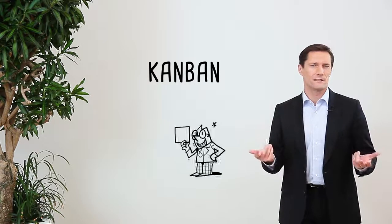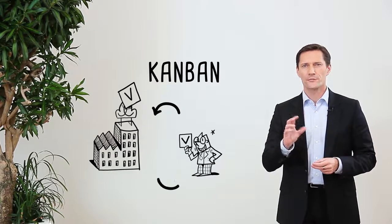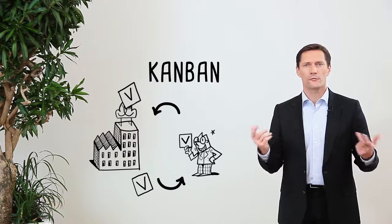A Kanban is a signal telling the supplier or the supplying process to produce and deliver a defined quantity of products. Originally, the Kanban was a label containing information on the production batch, like the item reference, its origin and destination, references of upstream and downstream processes, and the position in the manufacturing process. In addition to that, there were also sometimes information like the quantity of products and for sure the number of Kanban cards. Do you know why the number of Kanban cards is important?